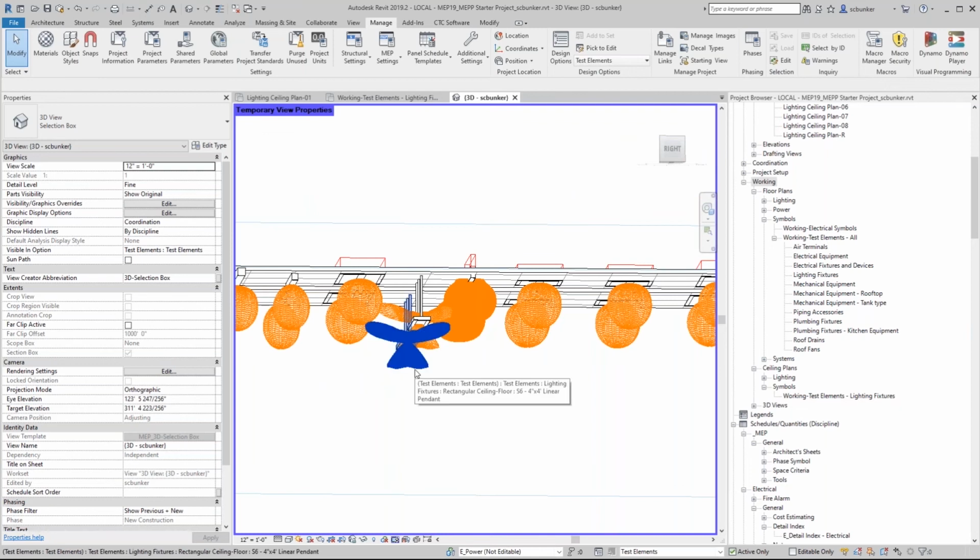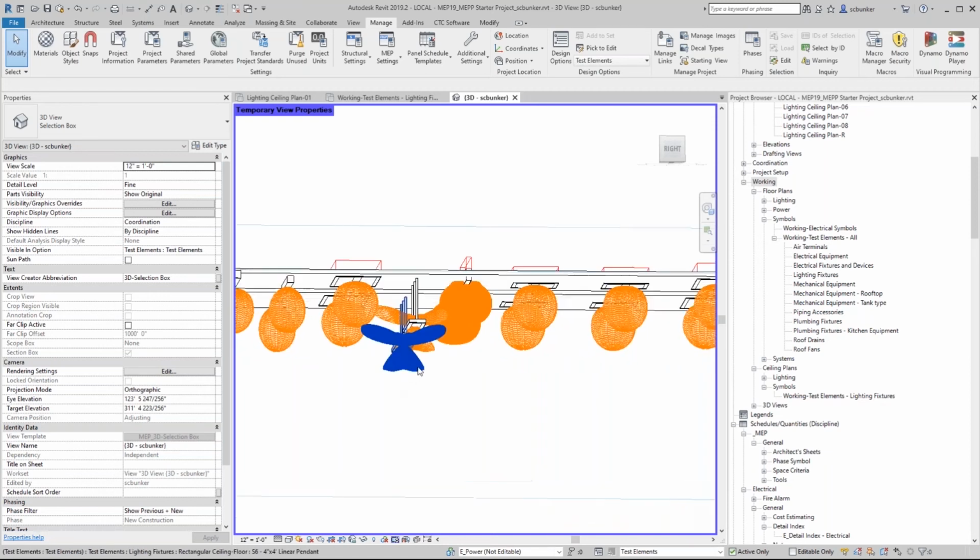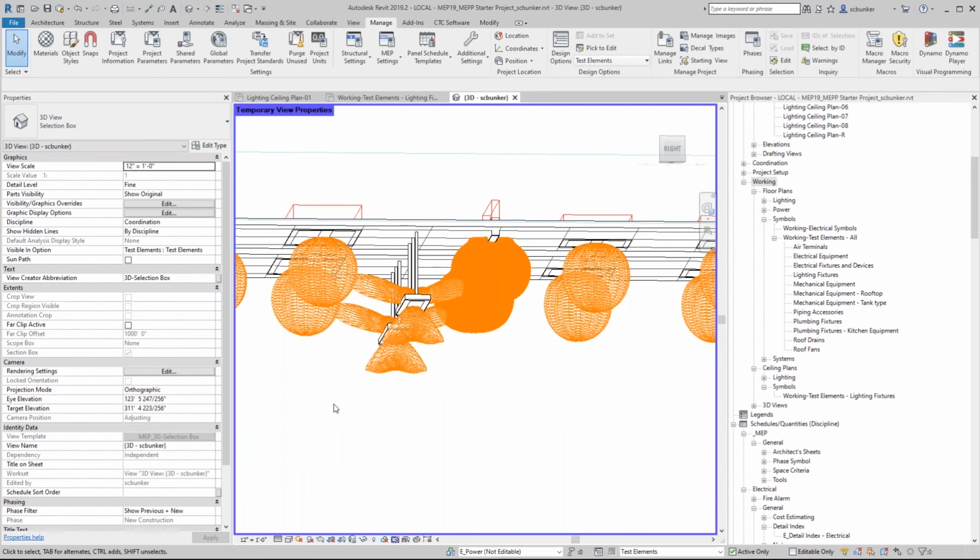These light sources work using Revit's built-in photometric analysis. I told you that we have some stuff set up already for that. And they also work using third-party add-ins like Illum Tools. Illum Tools is an add-in from the folks that make AGI 32. They work with all their rendering stuff and they calculate accurately.